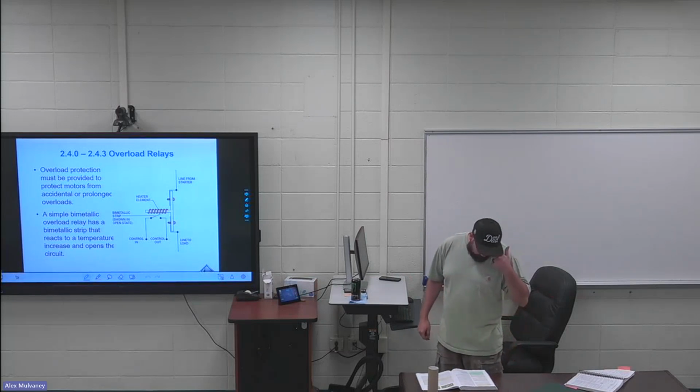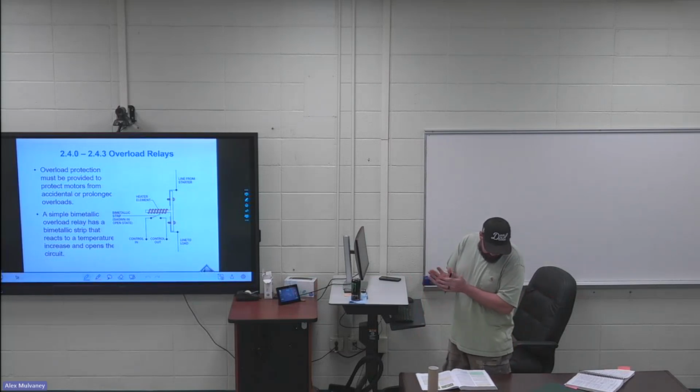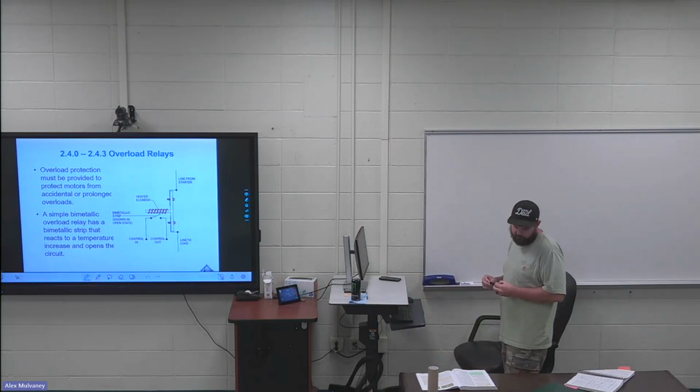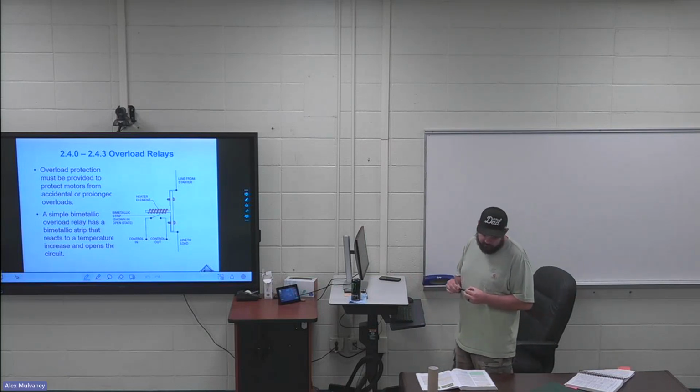Dual element or time delay fuses can provide motor overload protection, but have a disadvantage of being non-renewable and must be replaced once tripped. Fuses have to be replaced.